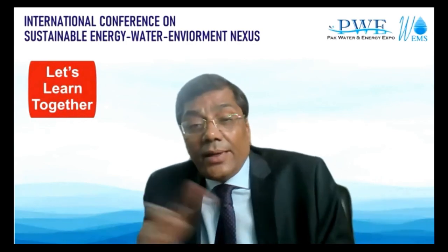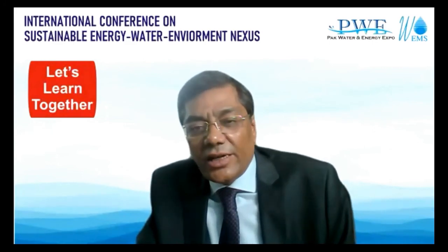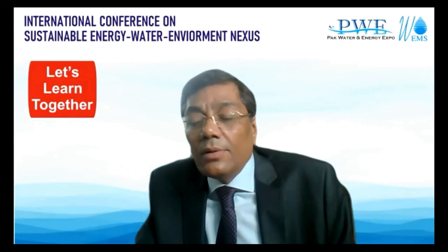If you have a constraint of area, like various industries in Karachi that have an issue of availability of area in their premises for installing the wastewater treatment plant, then MBR is a good technology. If your objective in future is to recycle the wastewater, you can go for MBR technology.